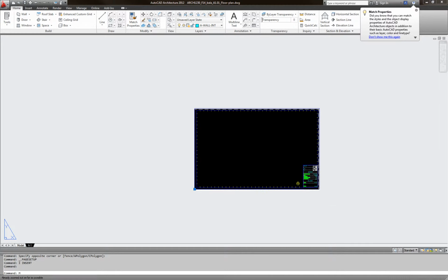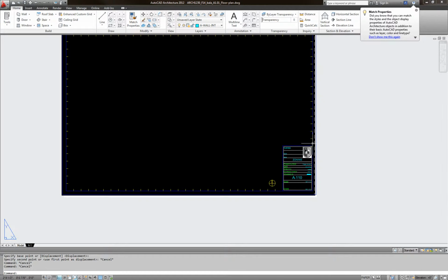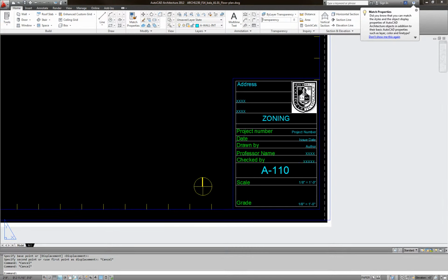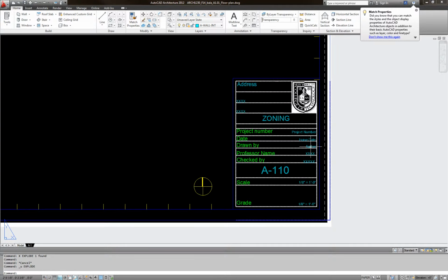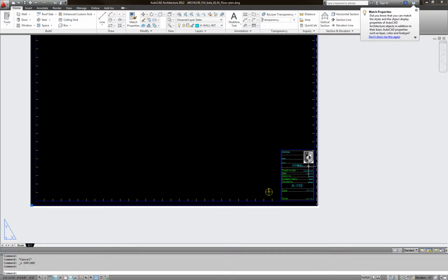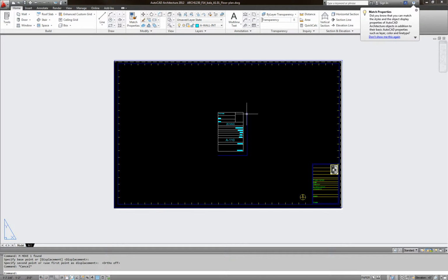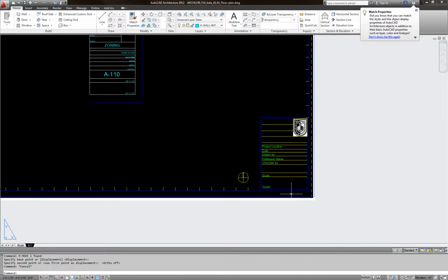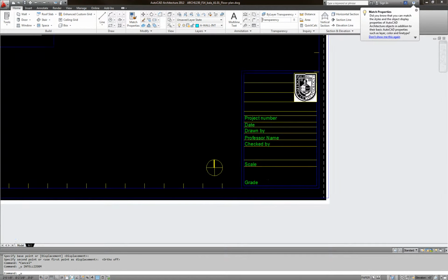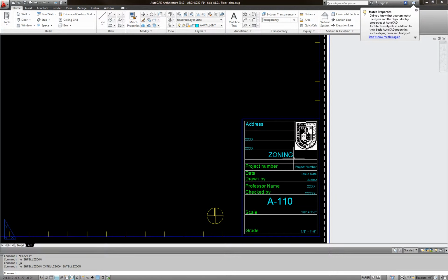Let me move this block so that it inserts in the right spot too. Now you can double click on this block and edit it. If you want, you could explode it by pressing Enter; then you can work with them individually, but I will keep them in a block. Let me show you this, for example. When I created this, I created these two lines so you could match them with this. And this white line, guys, will not print; only the depth points will.